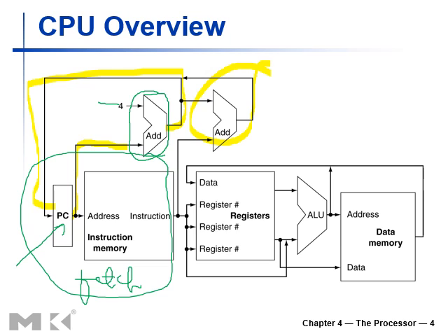After we've got the instruction fetched, we've got the machine code. The next step is to read the operands. Here we've got the machine code, and for MIPS32 we've got a 32-bit machine code for any particular instruction. The next thing is to read the operands. So this is the compartment that basically contains all our registers. The registers are physically implemented here.